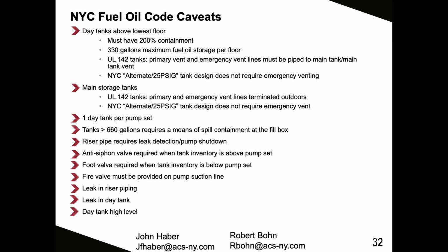UL 142 tanks require both the operating and emergency vent lines terminated outdoors. New York City alternate tank design, 25 psig rated tank, requires its operating vent be terminated outdoors. Also, the New York City alternate tank design tank does not require an emergency vent. One day tank per pump set. Tanks in basements over 660 gallons require a means of spill containment at the fill box. All basement tanks are in a 2-hour fire rated room minimum.